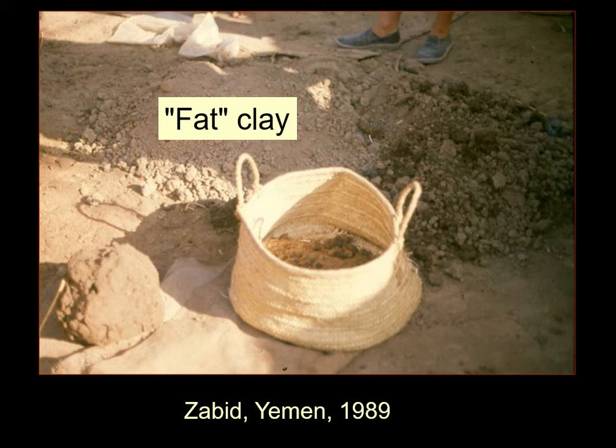And it will have difficulty outgassing during the drying and the firing, and so it'll probably blow up. So this is one of the reasons you add a temper. Now in this case, this is the temper, but it's not what you might think of a temper as being, a different material. It's a different clay. So you have a clay which has a lot of clay in it, and you have another clay which has not a lot of clay in it. It has more what we will call aplastic inclusions, and we'll get to what those are in a moment.